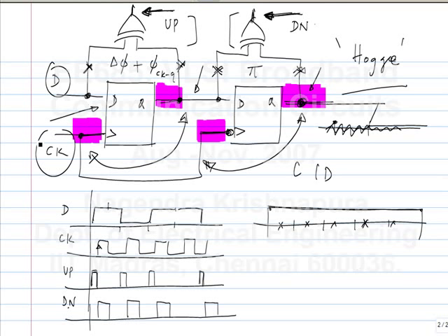So there are improvements to this. One of the ways is, see, when this is operating correctly, that is when the clock is aligned to the middle of the data, the up pulse is half a period wide and the down pulse is half a period wide. So the control voltage ripple looks something like this. Okay. So whenever there is a transition, there is a roughly triangular ripple on the control voltage. It is triangular because it's more or less an integrator because of the large capacitor. Okay. So there are ways to reduce the area of this and so on. The disturbances in the VCO are related to the areas under these pulses. So if you try to reduce the area of that, you get rid of some of the jitter problems in the CDR. So it's in one of the papers that I suggested for a presentation. Maybe one of you can present it. Okay.